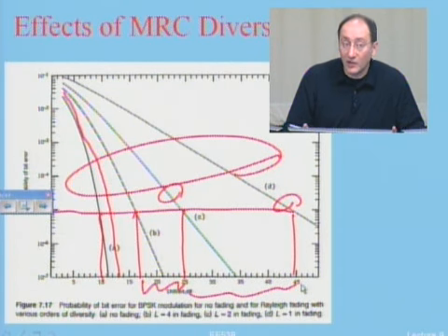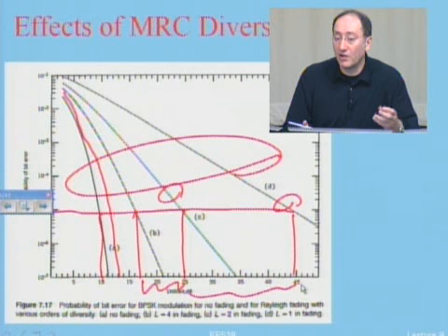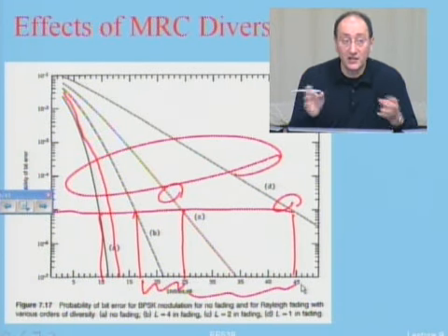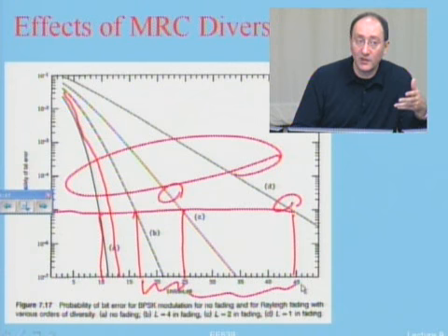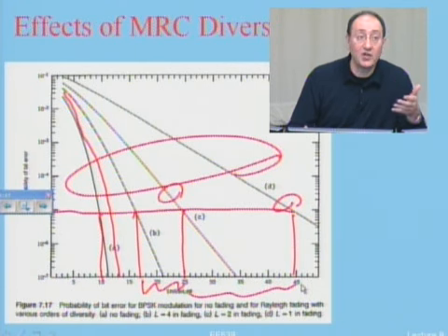Now, if you add multiple antennas, we had this physical problem, especially in the receiver, which is always a small gadget. How can you put many antennas? So I have to put them at the transmitter. If I put them at the transmitter, then I had this problem that I cannot create a maximum ratio combiner, which is the optimum combiner.